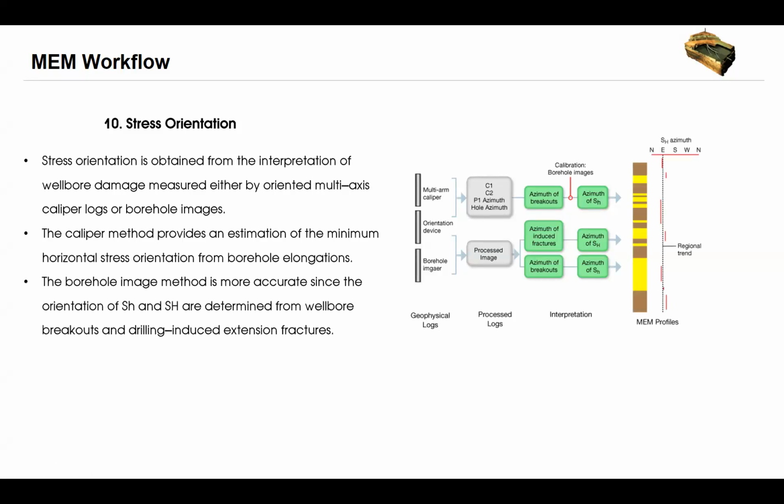The caliper-based interpretation methods are also designed to differentiate stress-induced elongation from other sources of wellbore damage, because we have a lot of sources of wellbore damage. We have not only the stress induced. Be careful when interpreting your caliper-based data. However, it is also recommended that the interpretation be checked using borehole images, FMI or UBI, when possible.